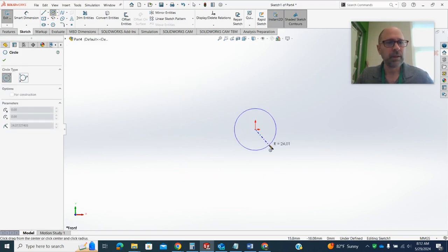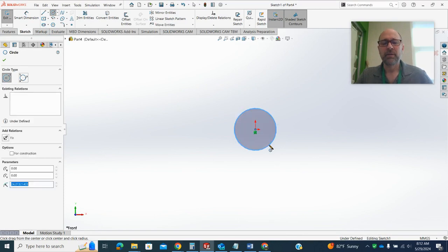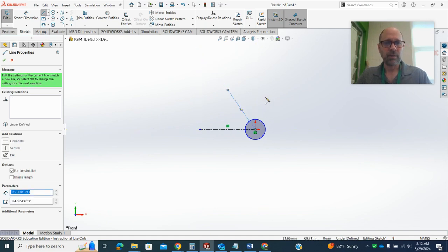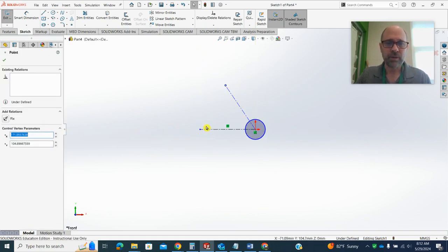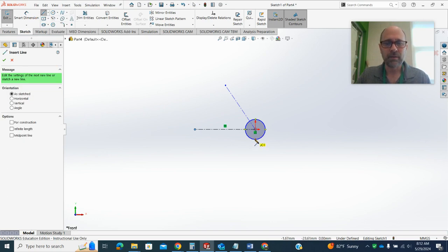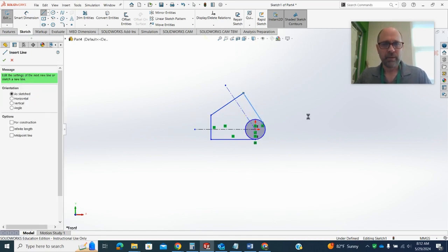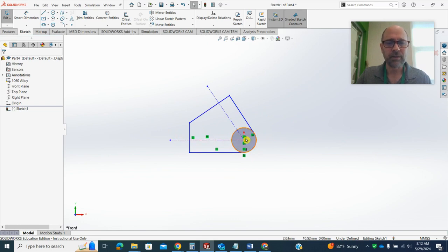Okay. And I'm not going to really pay attention to the actual dimensions until I lay the first dimension down. It will scale everything. Okay, so I'll start with these two construction lines. They're slightly different lengths. So then I'm just going to sketch around the outside. Maybe I'll just make the block feature first, and then I'll sketch the little rectangular tabs.